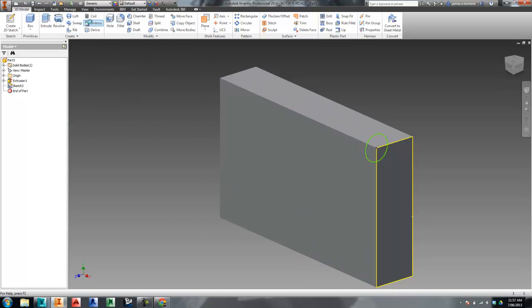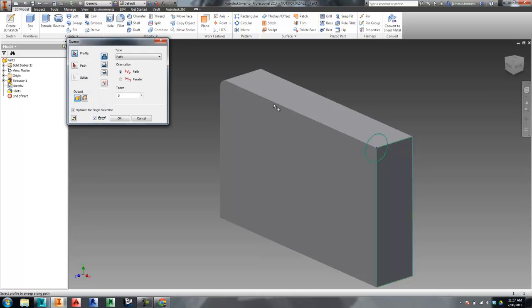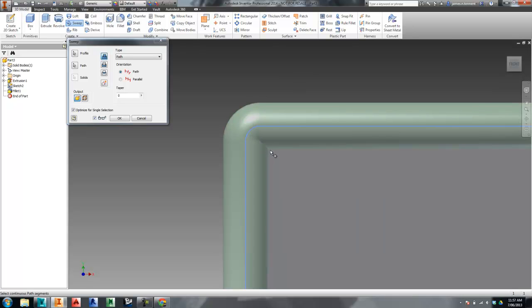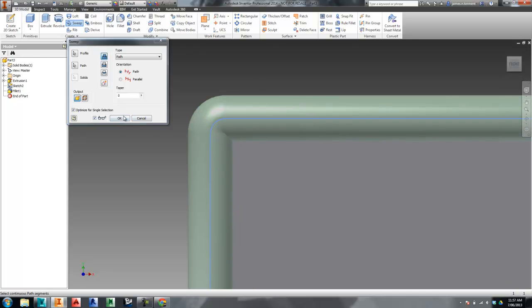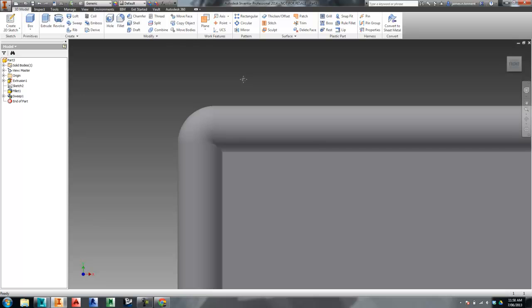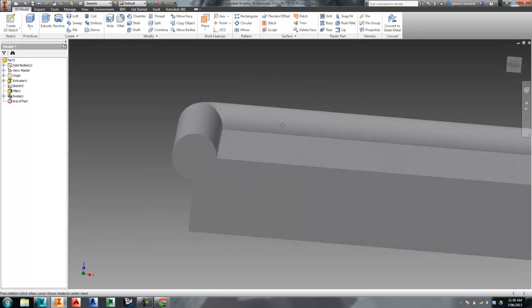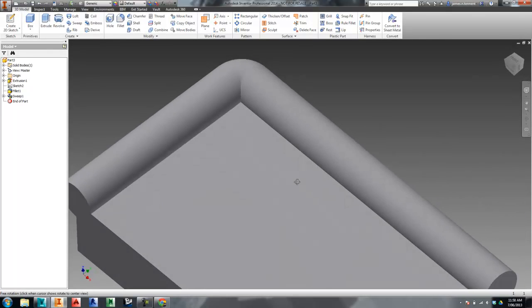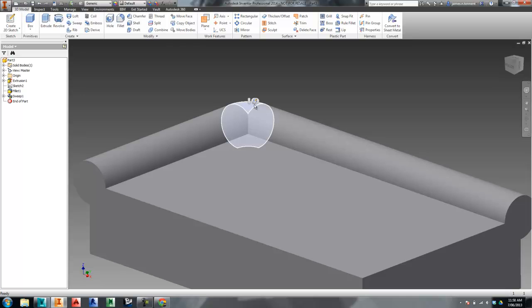The best part is, let's say I want to put a fillet on the edge of that, and I want to sweep around a fillet. In this case, this circle here would normally be far too big to be swept around that edge. But with the new features, Inventor really has no problem resolving these sort of sweep methods, because we have a new way of resolving them in the equations in the background. So you can see very, very nice tools, extremely good at resolving these sort of things now, and self-intersecting sweeps and curves and whatnot. These can all be resolved now without any problem at all.